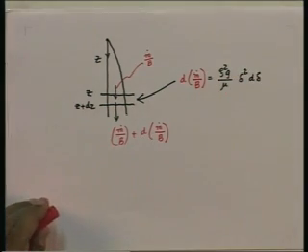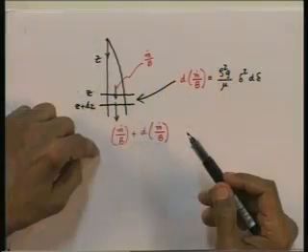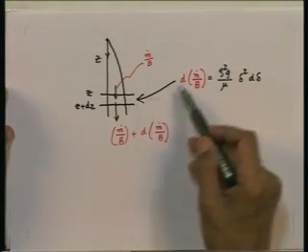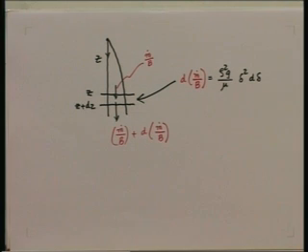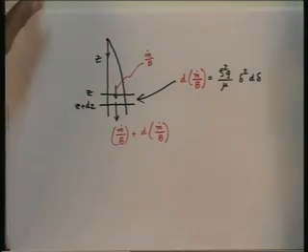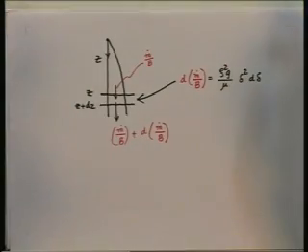So, if conservation of mass is to be satisfied, if the equation of continuity is to be satisfied, this is the mass balance, mass flowing in, mass flowing out. The difference is made up by the condensation which is taking place from z to z plus dz. This is how continuity is satisfied. Now, what remains is to apply the remaining fundamental law, which is the first law of thermodynamics. That is what we will be doing next.